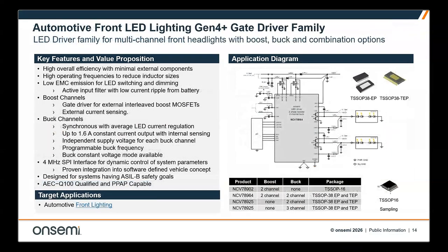So far, we focused on connectivity as the backbone of the software-defined vehicle. So this is where the story comes together. On top of the connectivity, our Generation Plus front LED lighting gate driver family is the driver that completes the offer. It covers the multi-channel front headlight with boost, buck, and combination options, delivering high overall efficiency with minimum external components, high operating frequencies that shrink the inductor, and low EMC emission for switching and dimming.